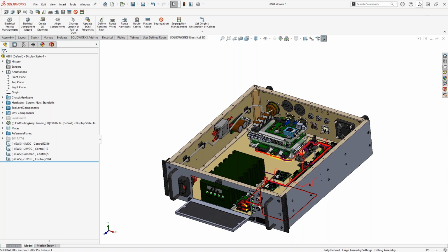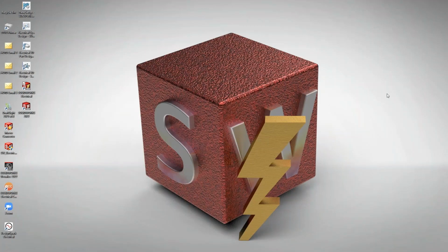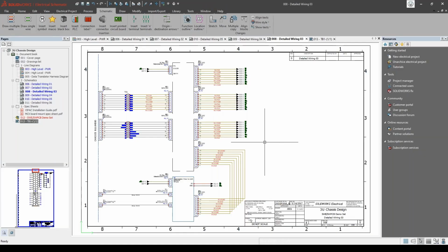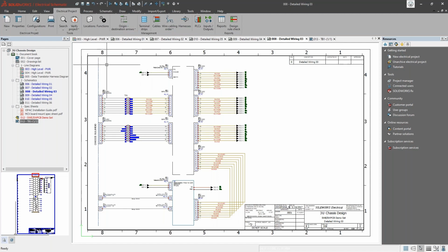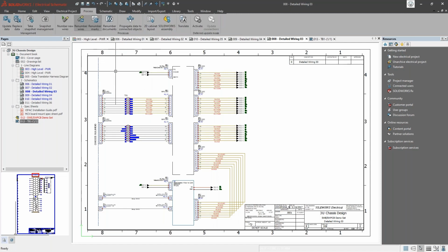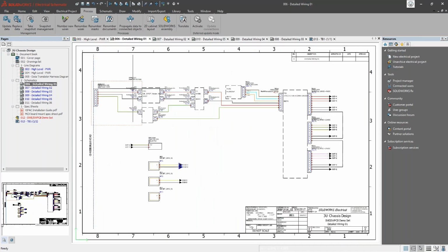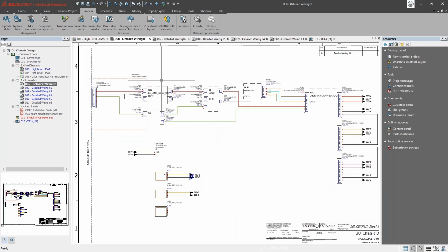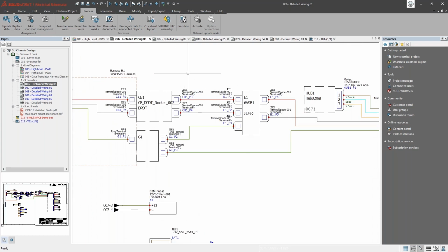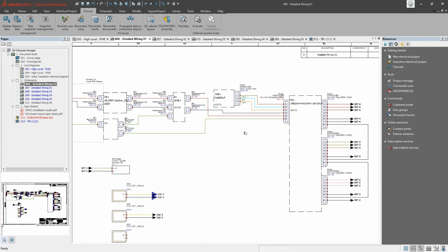All right. So going back to core SOLIDWORKS Electrical now. After we do our routes, there's a few other things that we might want to do and housekeeping that we want to do on the electrical side, I should say. So in the case of our electrical project, let's go ahead and find a good sheet to work with here. Control E is your friend. That's zoom extents. Always zoom out to where you need to go. And let's go ahead and search for a good spot to route or run our numbers.